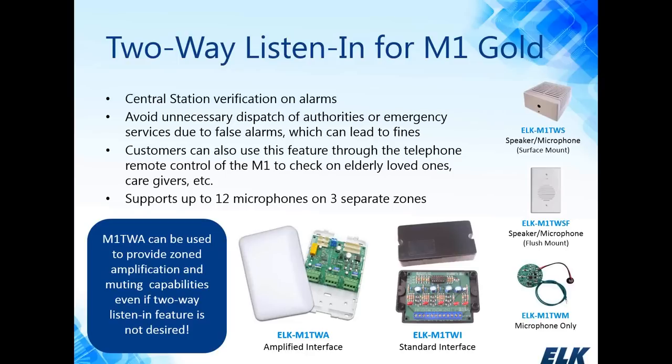The volume control, being able to connect your speakers and microphones to the one interface, as well as having mute capabilities. With the M1 TWI, you simply connect your microphones to this board, and the volume output through the speakers is controlled by the M1. We offer several different speaker microphone combinations. We have the M1 TWS in the upper right-hand corner. It's a speaker microphone, surface mount only. We have the M1 TWSF speaker microphone, flush mount into a single gang box. And then we offer the M1 TWM, which is the microphone only.